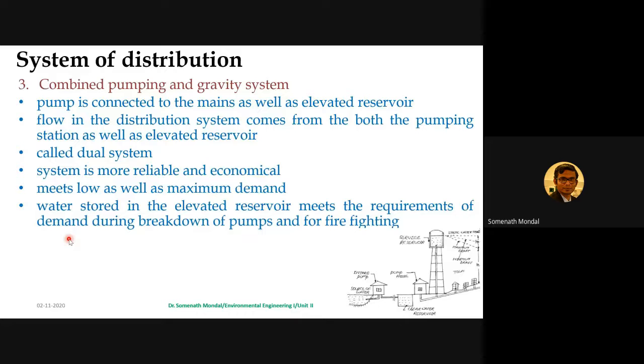The intermittent system is not preferred. Because of alternating wetting and drying, the cost of maintenance increases and the chance of rusting increases. During non-flow periods, because of stagnation and leaks, the chance of pollution is increased, and more wastage of water can happen since people have the tendency to store more water than they need. And next time when water comes again to the consumption point or the tap, they will simply throw away the stored water and collect fresh water. So in the process of collecting water, they are wasting some amount of water. So wastage is more in this case.